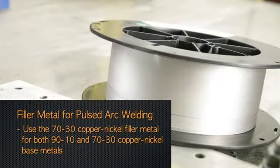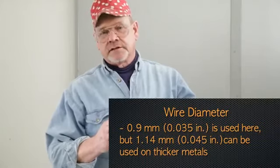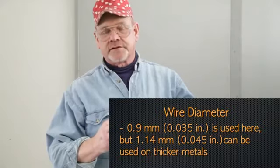In this case, we're using 35 thousandths of an inch diameter wire. There are other sizes available, such as 45 thousandths of an inch, 1/16 of an inch. The larger sizes are typically used on thicker materials where greater productivity is desired.